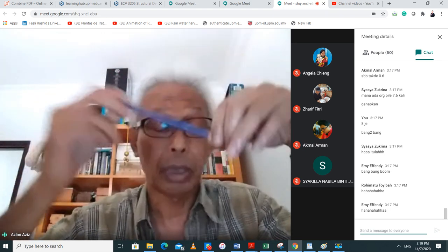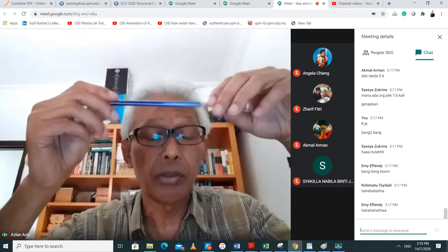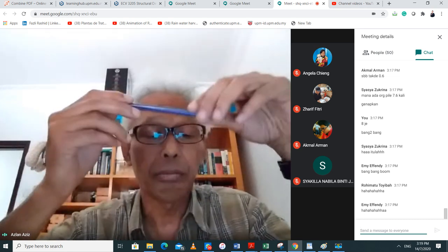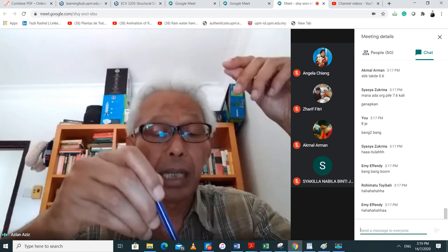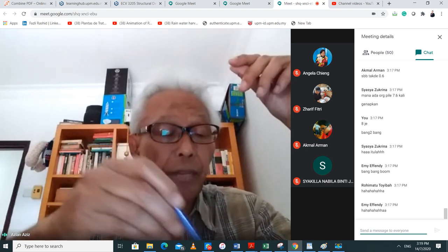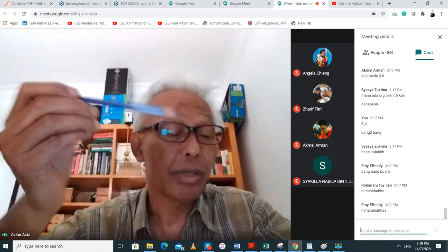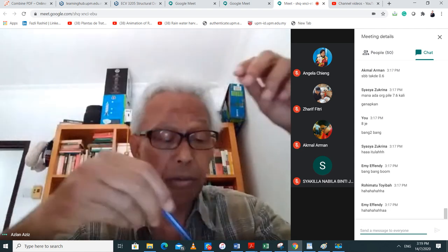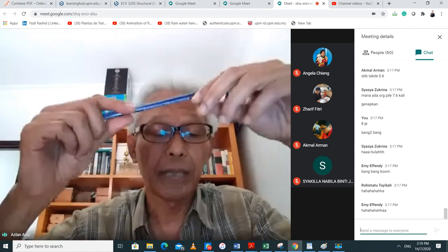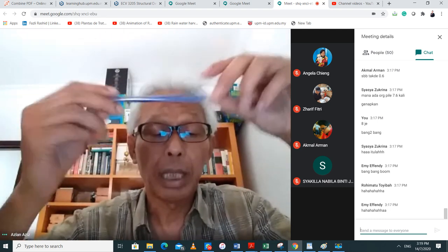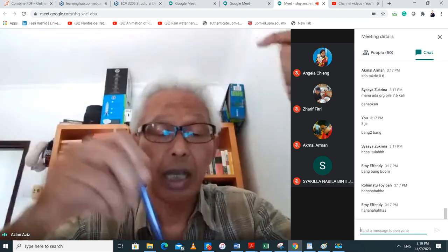Okay? Next column. So you calculate A sub B Q sub F using the values that you just calculated. For the first one, it is 0.45. A sub B multiplied by Q sub U or Q sub F. 535 multiplied by A sub B. A sub B is the diameter you already calculated a few minutes ago. So 0.45 multiplied by 535, you get 108. And then the shaft friction, you add that up to this shaft friction, A sub S F sub S, and you get 130.